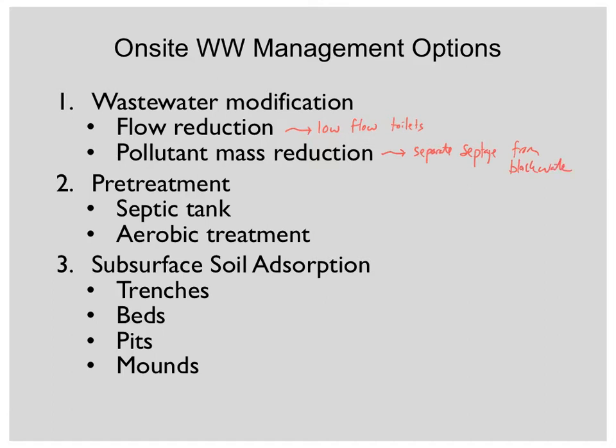And then if we go forward, we think about pretreatment with the septic tank. This is going to be an anaerobic process. We'll learn more about that. We can also think about aerobic treatment. So septic tanks are anaerobic. There's also aerobic possibilities, but much less widely used.